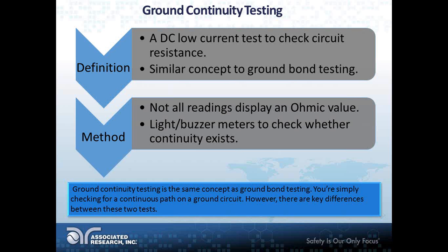And sometimes for a continuity test, I'm not talking about our units in particular, but a lot of different ways to check continuity out there, you might have something like a light buzzer or battery buzzer combo thing. You might have seen these things where you have a little pen with a light on it and it's got a clip, and you would put the clip on the chassis, much like I put that black lead on the chassis of the product in the video, and then you take the little pen and apply it to your ground pin or another grounding point, and if the light goes on, it's telling you, hey, you have continuity.